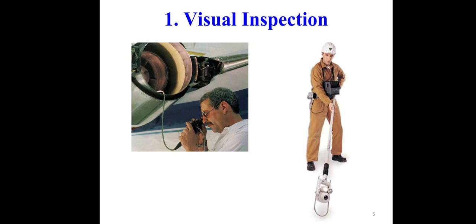Seeing is believing, and the art of seeing is the visual inspection technique. Visual testing requires adequate illumination of the test surface and proper eyesight of the tester. The test specimen is illuminated and the test surface is observed and examined. Whenever required, optical aids such as mirror, magnifying glass, microscope, video camera and computer vision systems can be employed.